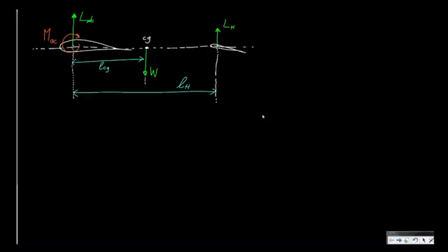Actually, it's smaller than 0, but it's indicated here larger than 0, because for our signs we will always use this direction, nose up, as positive, and this is how we draw the moments. In reality, when there's positive lift, there is a negative moment. So MAC, as we have drawn it now, will be smaller than 0. But this is the direction which we use for all moments, and that's also how I draw it. So this is the total situation of this aircraft.